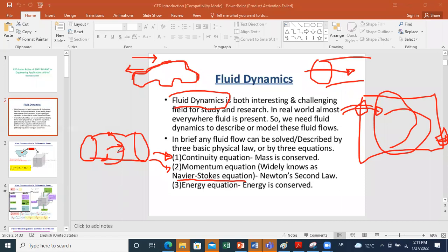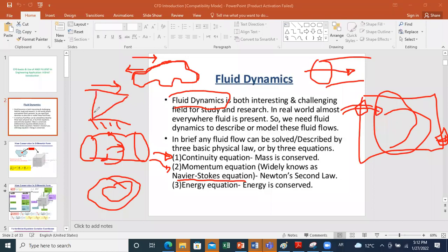You have learned also how to determine, let's say, flow in between concentric cylinders. So this application is also widely used. So how we establish the profile of velocity in concentric cylinders, how to find flow variation between two parallel plates. If I have one fixed plate and the other is moving, then I can obtain a linear profile of velocity. So these are simplified solutions for very simplified problems.